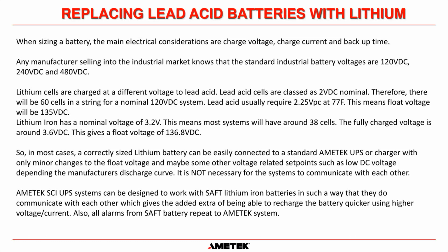And what it also gives us is the added extra of being able to recharge the battery quicker using a higher voltage and current. Because the BMS is a relatively complex piece of software, it can communicate with the UPS if it is designed correctly and say, hey, wait a minute, I've been discharged. I can accept a much higher voltage current to get me back up to float voltage quicker. A lead acid battery can't do that, obviously.